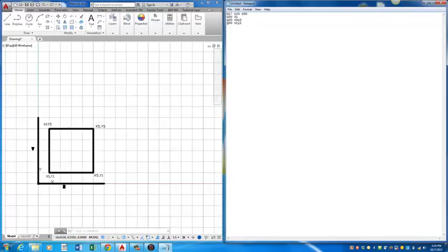My next move, I'm going to do a G01, Z0. What that's doing, since I moved to this point, is putting my pen down on the paper at a feed rate of 60 inches per minute. F60 means 60 inches per minute. So that's how fast it's going to feed there. That's the difference between the G00 and the G01 command. With a G01 command, you're allowed to specify a feed rate. G00 is just full speed.